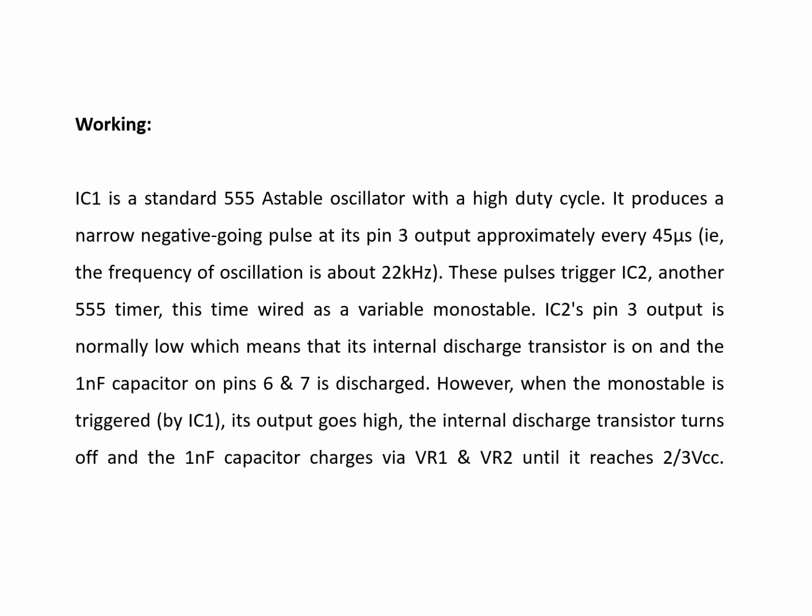So the importance of soft start is to provide low inrush current and to smooth the heating of the element, which makes the lamp run with longer life and better reliability, and reduces the electrical stress on the transformer and MOSFET.